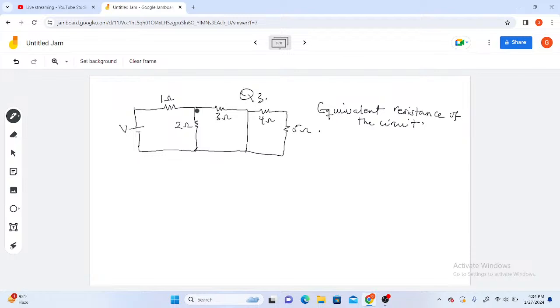You just take your time, and if you have a voltage source, I told you you have to get the effective circuit before we can proceed. So this voltage source here is going to produce a current I here. Then a current I will pass through this side, through this 1 ohm resistor, because it has no other option. It's only one way. Upon reaching here, there are multiple paths, either pass here or they will pass here, right?